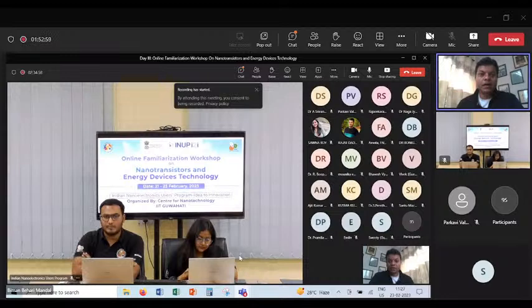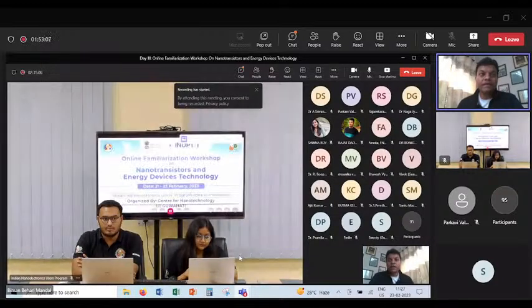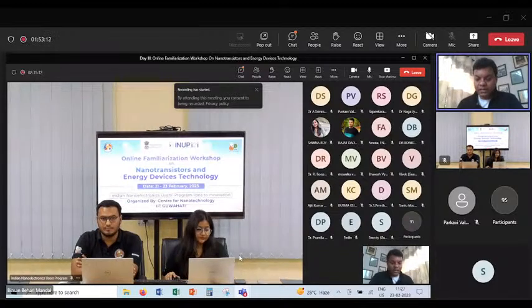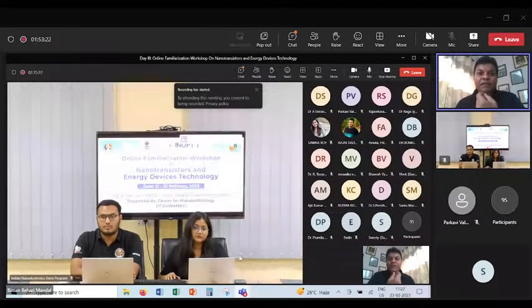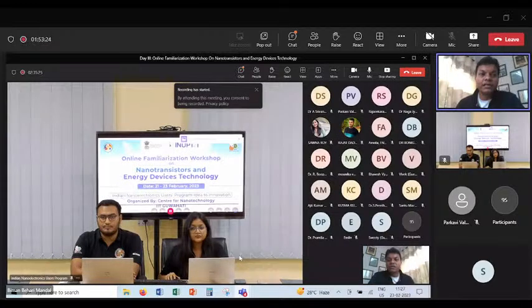Okay, thank you. The resolution, so now it's a very unique, very important question. As of now, the resolutions are down to 150 microns, but there are machines which have now come to the market which go down to a couple of microns. But again, the limitation is you cannot use cells for all of them; for polymer printing, you can use them, because the cell has a specific dimension. And if you reduce the nozzle size to very narrow, what will happen? A lot of shear would be produced and the cells would die.